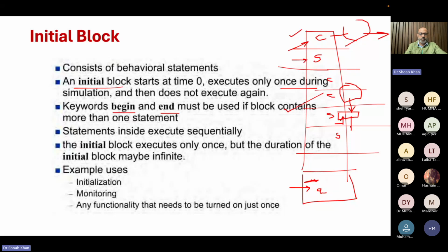The fixing will become very difficult. So inside a block, whether it is a sequential or a combinational block, the statements happen sequentially, but from outside they all start at zero simulation time. All blocks start at zero simulation time.